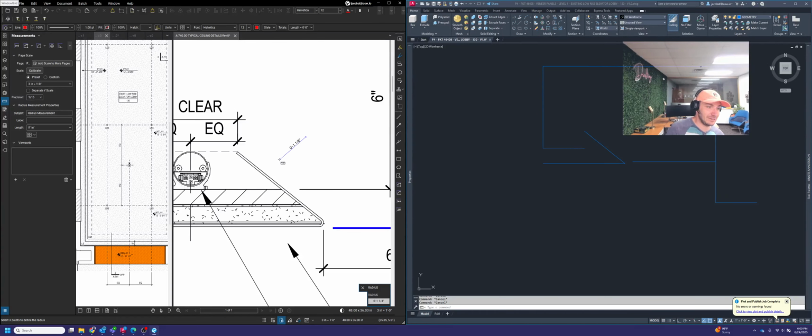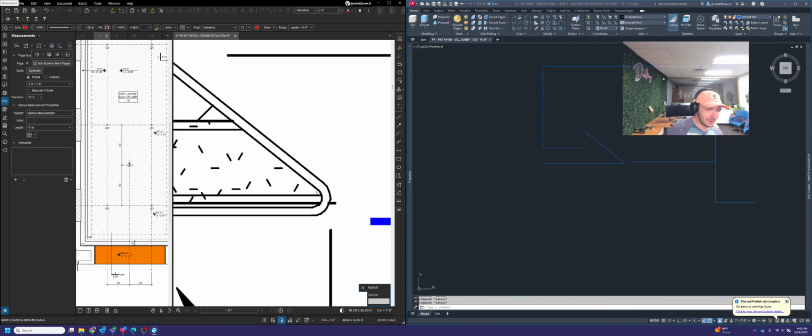It's going to ask you to draw the circle. There's a different tool on top of that though. If you go to where it says radius and click the drop down, you can go to 3-point radius and you can grab 3 points on a curve, and it'll give you roughly what that radius should be.